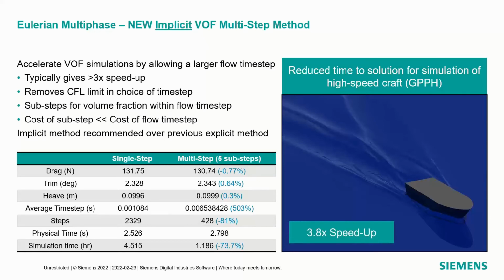lot faster. And you can see for a single step versus a multi-step, you have a lot of the same output variables. You have a very low difference in these output variables, but you have a very high difference in your simulation time and simulation steps. So this is a good way to speed up a simulation like this.